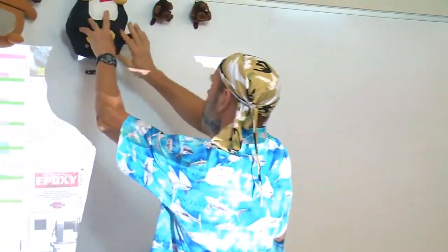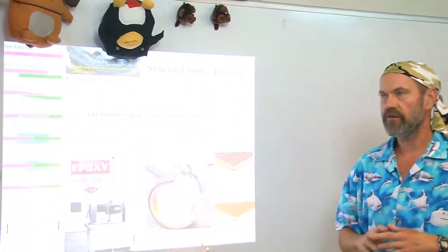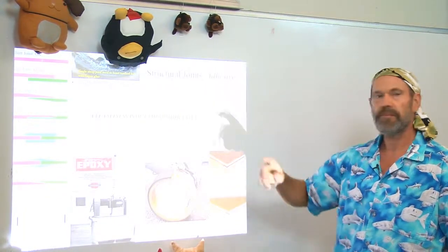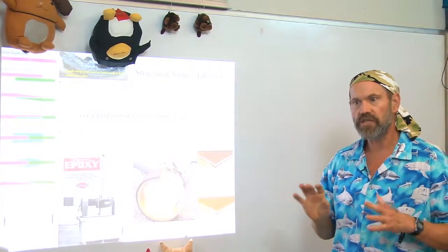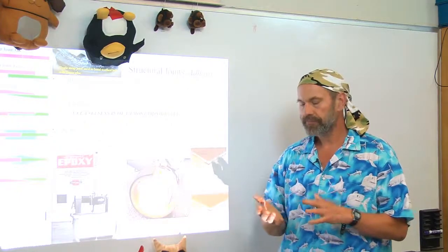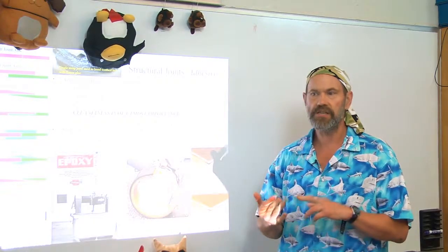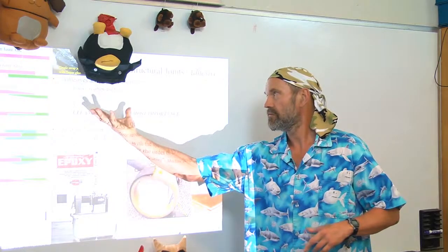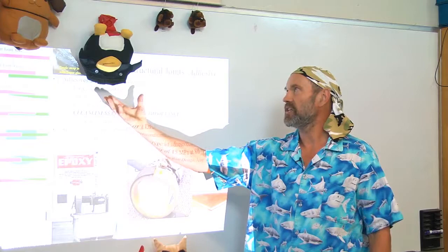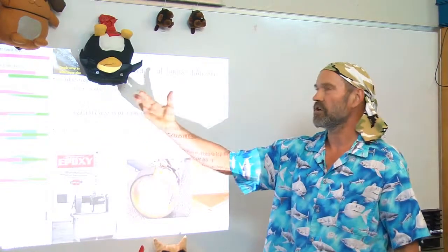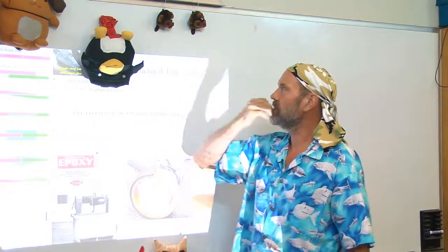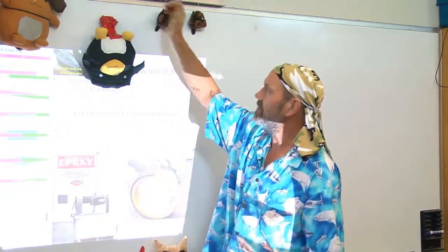When done not properly, they will tend to slowly creep and fall off. You can see them slowly moving there. If you're going to use an adhesive, you have to pick the proper adhesive for the job. There are many epoxies and acrylics that will hold and hold and hold. And other ones, particularly when it's warm, will start to ooze. Or what happened with this guy here, and you can say, why is it holding here but not there?